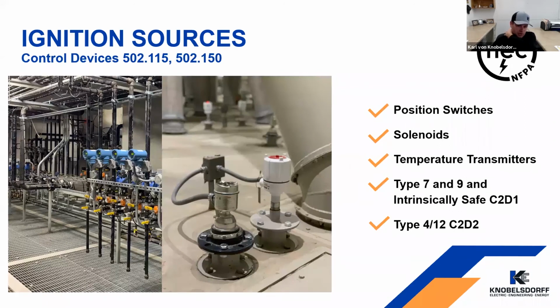Control devices are another ignition source. These are looked at in 502.115 and 150. Devices that fall in this category are position switches, solenoids, temperature transmitters. If we're dealing with a class 2 division 1 location, we're going to be using type 7 or 9 NEMA ratings or intrinsically safe. If we're in a class 2 div 2 location, now we're going to get by with types 4 or 12. So again, a 7 or 9 rating is going to be a more expensive device versus having a NEMA type 4 or 12. So again, if we can get that rating down to class 2 div 2, it just allows less expensive components to be used in your facility and helps make those new projects a little more economical.